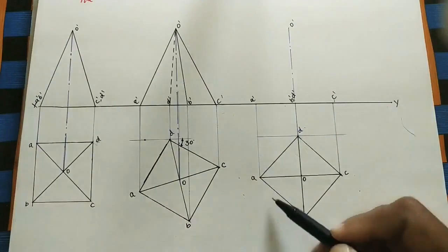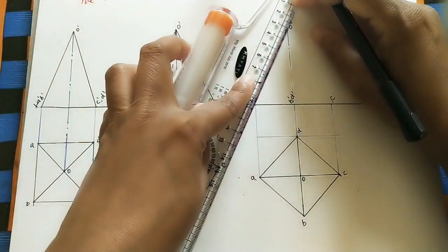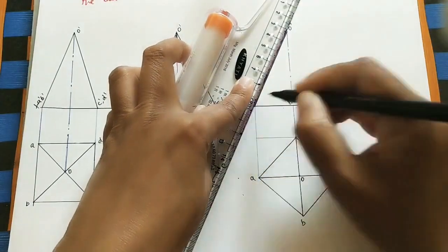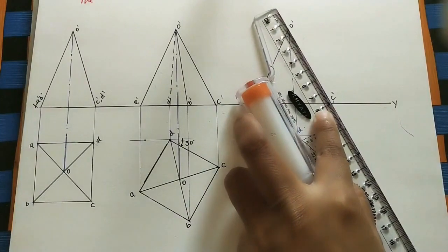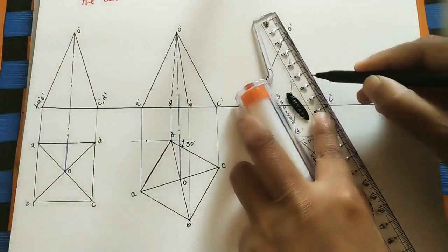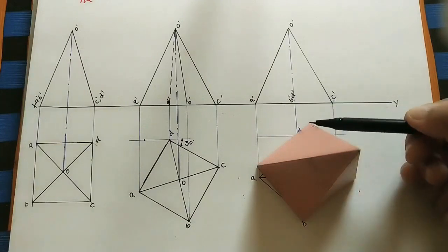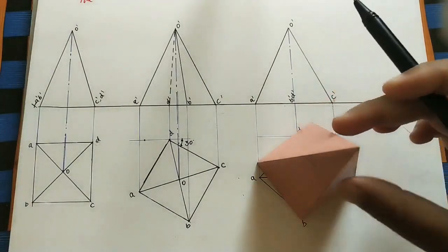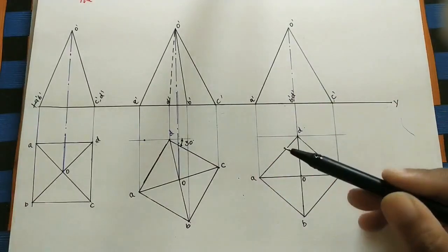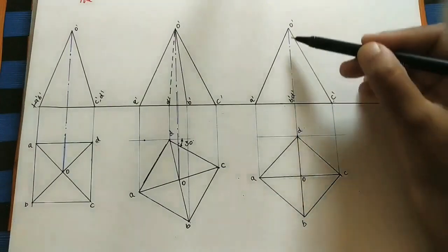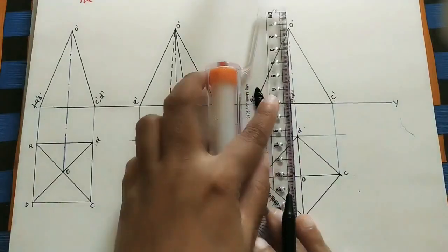The corner A we can see from the front. Do the continuous line. And C corner also we can see the slant edge. So from the front we can see this edge, but we can't see this edge, but both are coinciding on the axis line. Okay, so here this edge and axis are coinciding. So here this is visible, that's why do the continuous line here instead of the axis.